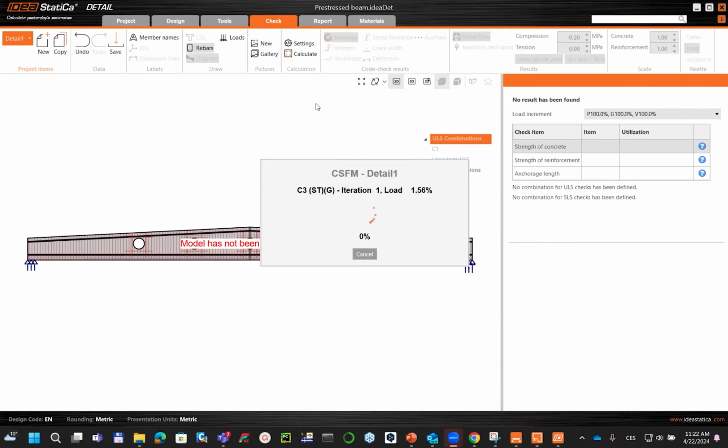You have 3 or 4 minutes left for this seminar. So I will go very swiftly through the results and show you the stresses in the tendons, how the structure is deforming, and the stress concentration around the openings. There is a concentration factor around the openings that cannot be captured in the 1D element solution of beam theory. And also how the reinforcement is utilized.